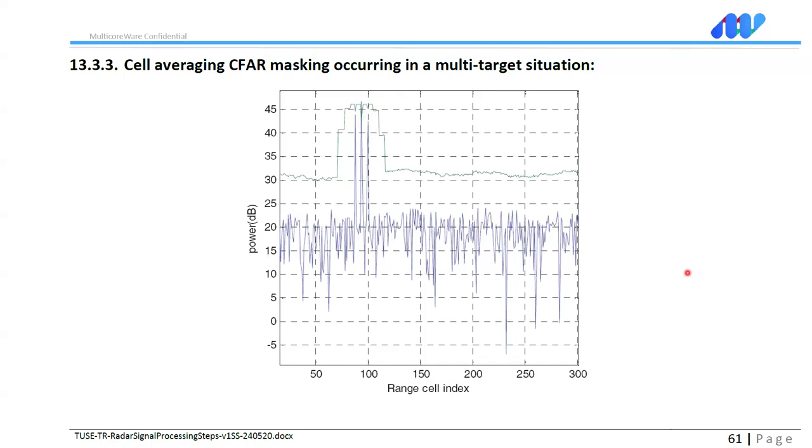And for example, for the BU-MTB case, for the mobility transportation applications, it becomes very vital. You have to have a very good CFAR implementation. It determines your whole performance for the product, and whether it will be accepted for the level 4+ autonomous vehicle industry, where radar needs to quickly detect and differentiate in milliseconds a pedestrian appearing behind a large bus.